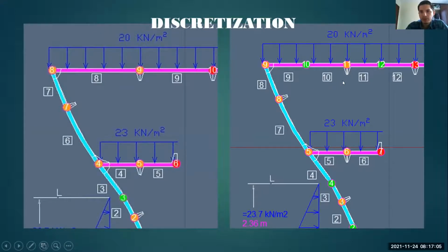The second discretization was made after an analysis of the applied loads, after the equivalences of forces and moments. We saw that the main deck elements had higher forces and moments than the bottom of the frame, so we put an intermediate node there.